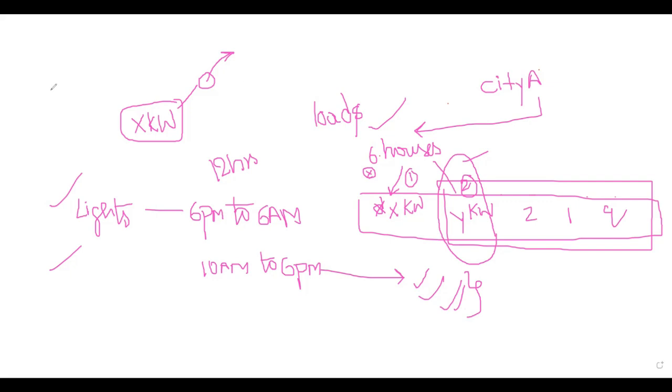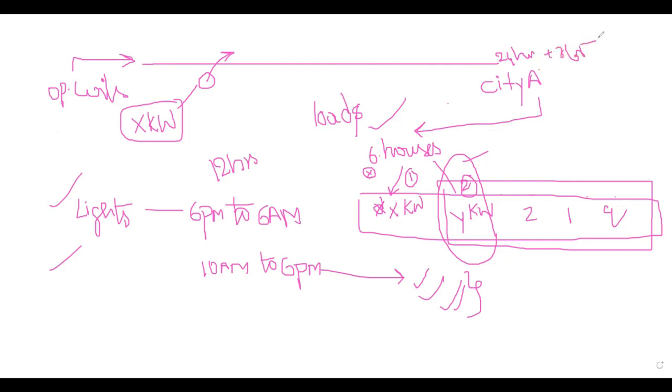And if you see the relay operating coils and master trip relay, generally we have trip circuit supervision. These are continuously monitoring relays. These relays generally require continuous supplies, so these loads are continuous for 24 hours, 365 days. These are continuous loads, if I am talking about the substation. And the others are the non-continuous loads.